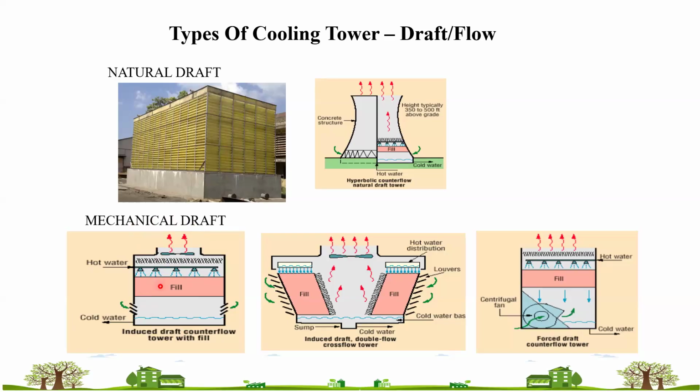So they are widely used. You can get your cooling tower from 20 to 30 TR to let's say 500 TR, 600 TR. You can get any size of cooling tower in the induced draft counterflow type. Fans might vary, like in a 1000 TR cell, there can be several.